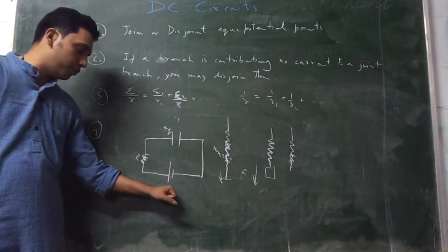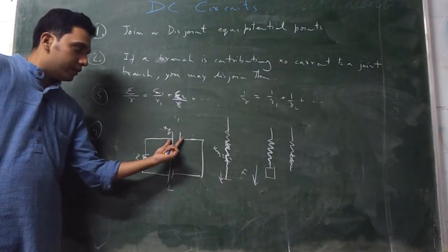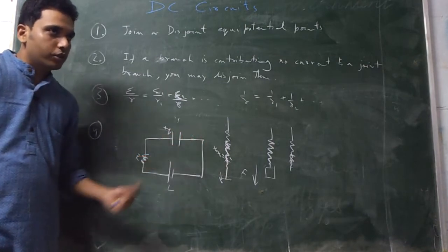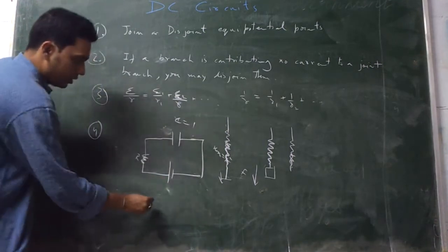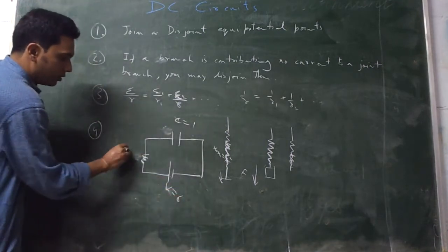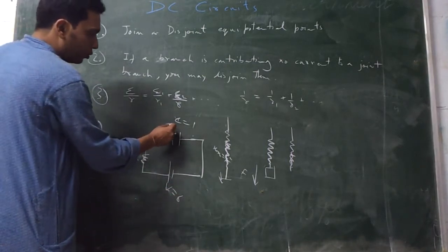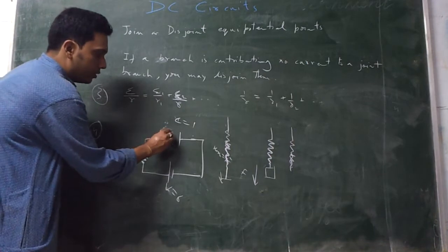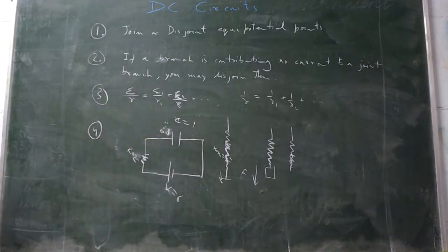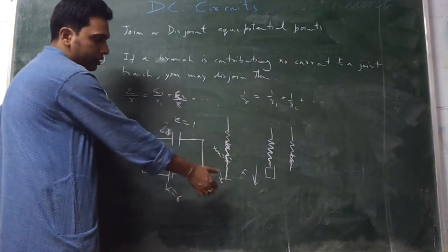Here also, if you have put a voltage V, it is same as putting a constant force, and first it was balanced at 0 charge, now it will be balanced at some other charge. Say this capacitor has a value of 1 unit, and this voltage is 6 volt, and this resistance is 2. The final voltage on this has to be equal to 6 volt. The total charge on this will be equal to 6 coulomb. So Q is equal to C into V. Now this 6 is same as the spring has stretched 6 centimeters and again come to rest.